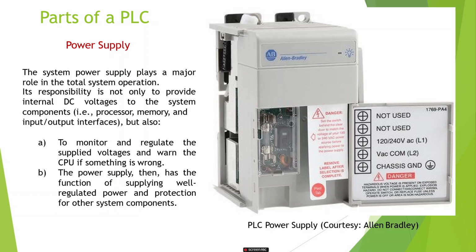The power supply supplies DC power to the other modules that plug into the rack. With larger systems, power to field devices is provided by external AC or DC supplies. For small and micro PLC systems, the power supply is used to power the field devices.